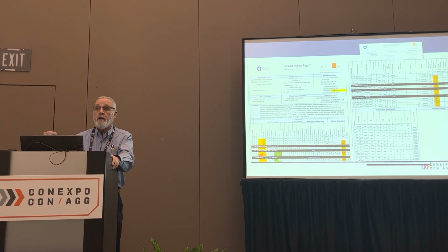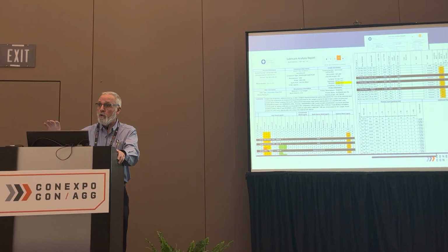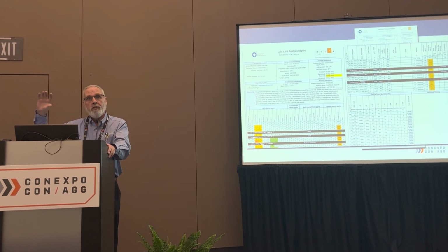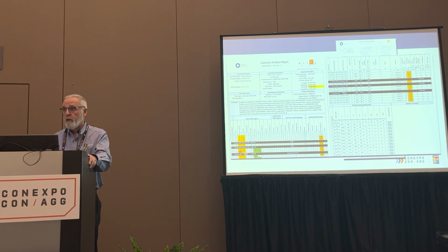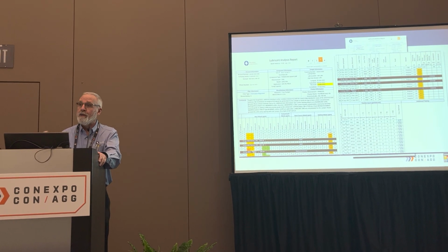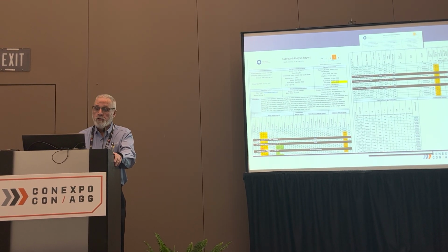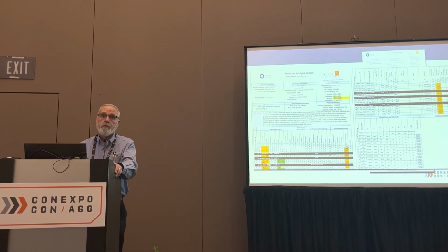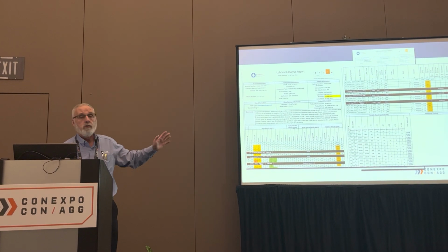You're probably going to see an increase in copper simply due to the leaching of the brand new oil cooler. So that next sample, you can see a little bit of increase in copper. Maybe the next sample, that copper level would start to come down a little bit, eventually go away. But it really makes a huge difference when you're reviewing the fluid analysis report at a glance. That maintenance planner and maintenance manager can look at it and say, I'm not worried about that little bit of increase in copper. It's probably leaching because we just now put a brand new oil cooler on it, and that history is right there in front of them.